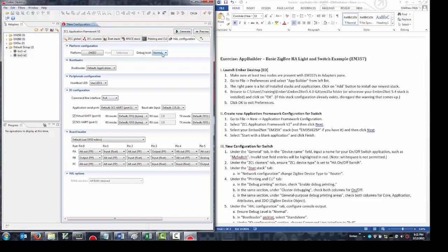Then we're going to set up the bootloader configuration, which we want, in this case, to be standalone. The standalone bootloader was chosen because the application bootloader requires different data flash depending on your hardware, so the example becomes easier to adapt to different boards if you choose the standalone bootloader. Note that if you're following instructions and you happen to have a different board type, don't worry, you can just set the chip type to be something else, but you may end up needing to change some of the GPIO settings when you adapt this to your particular hardware.